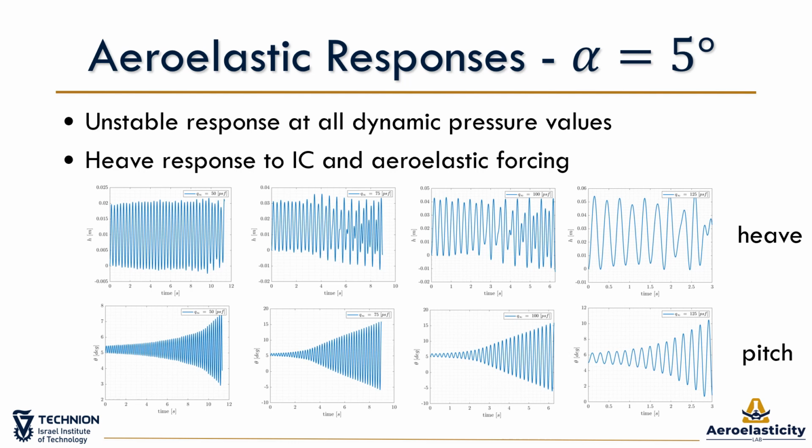In the heave response, we can identify two different phases. First, we see the response to initial condition at the heave natural frequency, and as the pitch oscillation's amplitude grows, the aeroelastic forcing becomes more dominant and the amplification at the pitch frequency also grows.